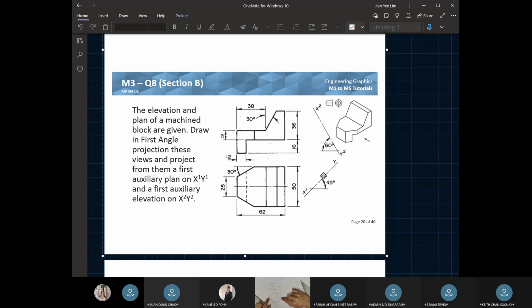Remember how I mentioned you want the datum to be at the bottom of the shape if it's not symmetrical. Well, if your shape is symmetrical, you want it to be in the middle. Since it's symmetrical, you can base everything about the middle line. As you can see here, before and after the datum, the shape is the same.